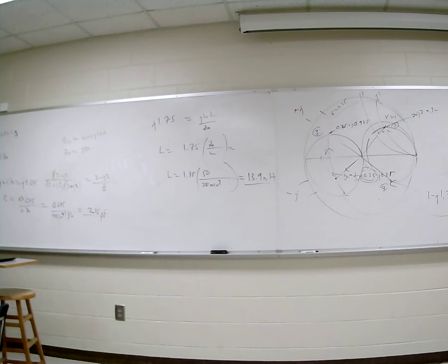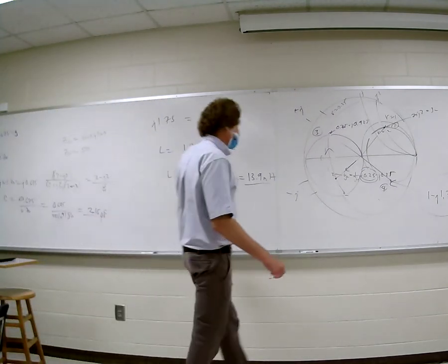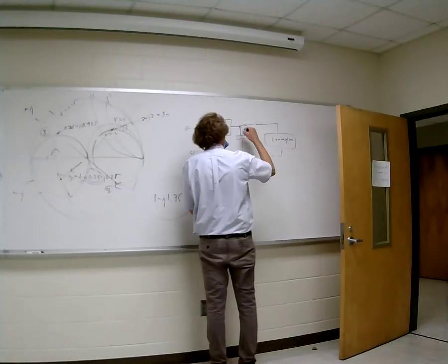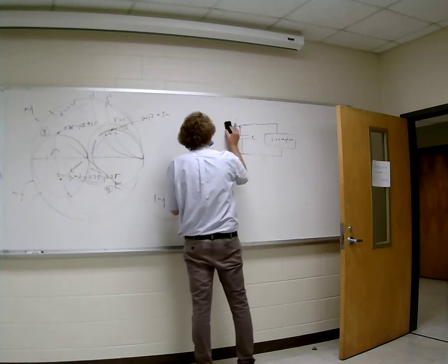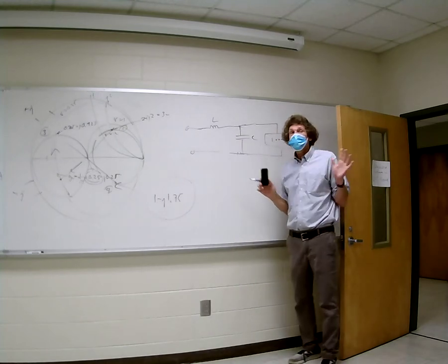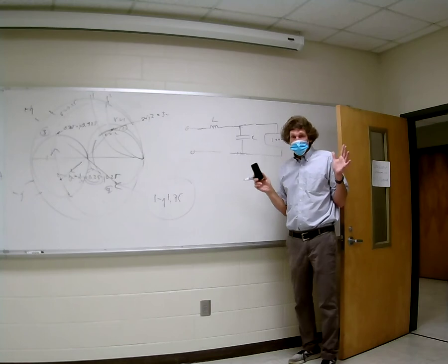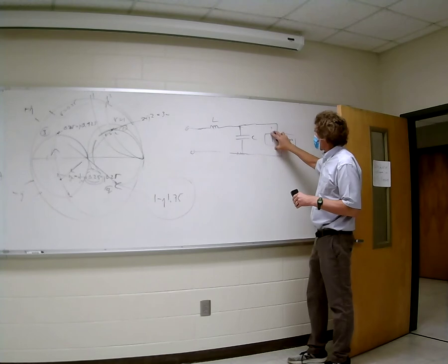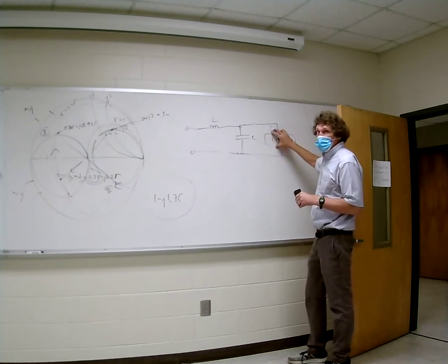Now notice what the elements look like on this one: we got a parallel capacitance and a series inductance, and that's the way you want to do this usually. You got a parallel capacitance, that's perfect. That means this capacitor will block DC shorts in case you have an offset voltage. Then you have a series inductor, L. That's perfect too, because at DC inductors look like short circuits, and depending on what this is feeding over here, this 100 plus or minus j something, it may be an amplifier that requires a DC offset.